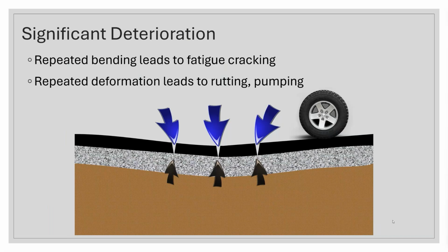It's going to pull subgrade soil up into the surface, and it can also leave some of that debris, grit, not really gravel size, but some of the sand and the silt can get up into those openings where the cracks are. And then during different seasons, in the summer, the pavement's going to kind of swell and those cracks will tend to close. And if you've got debris stuck in those openings, it's going to push against it, and then you create more fracture, more breakage at the edges. You have rutting, you have pumping, all kinds of bad things happen. So we can tell immediately that we definitely don't want to have any of the drainage issues.